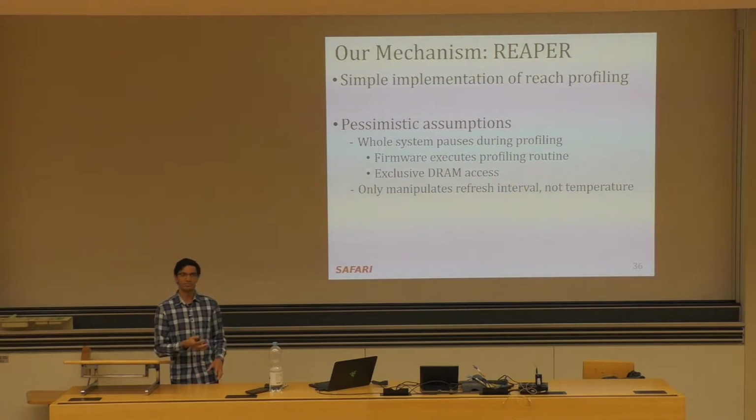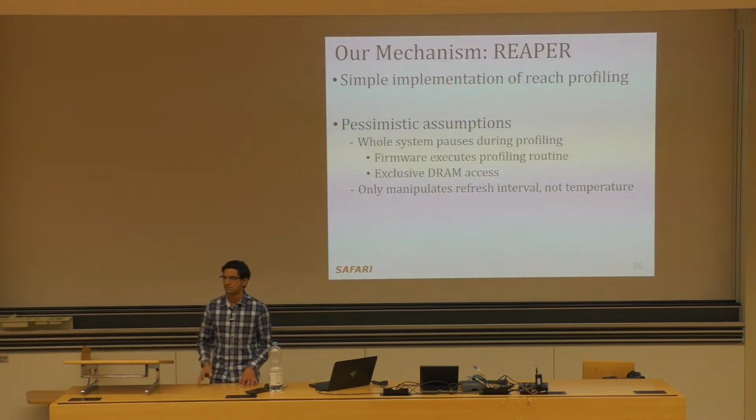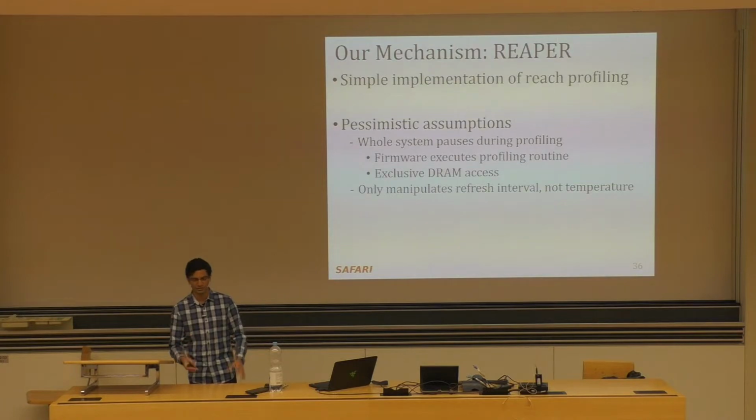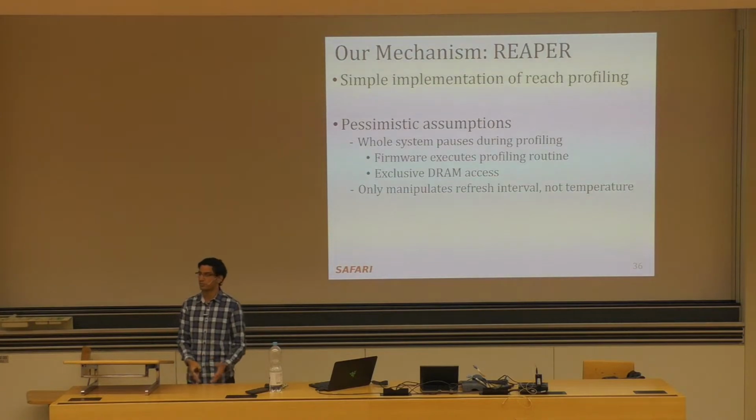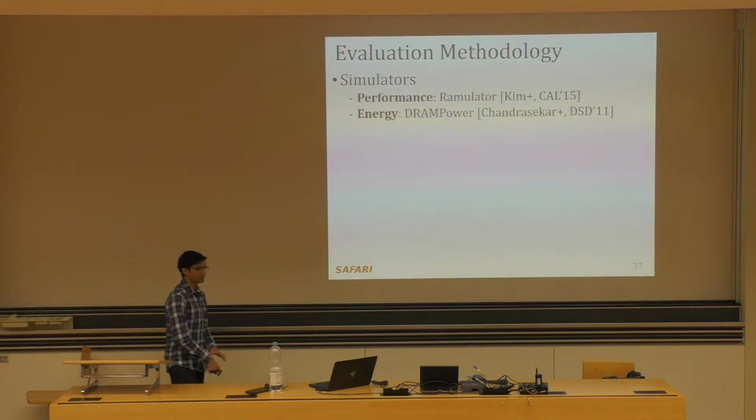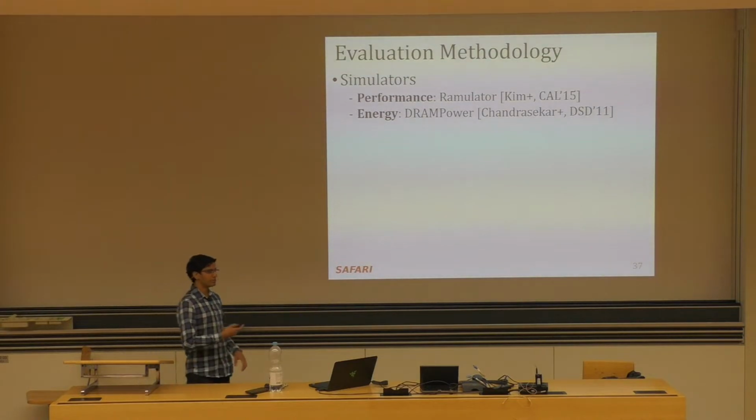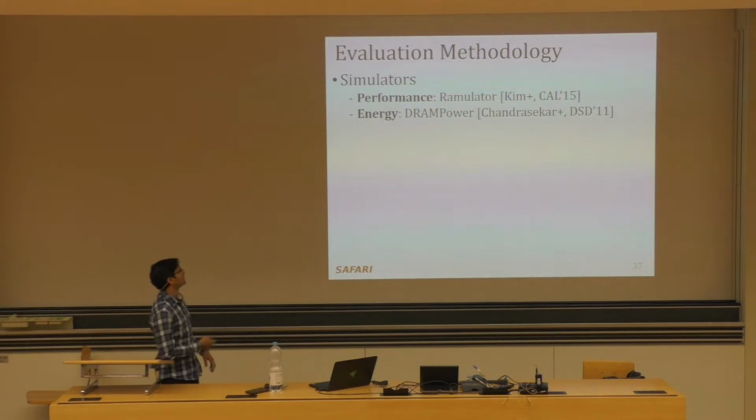And we believe this is a reasonable assumption for devices in the field, because controlling temperature, unless you have some lab setup and apparatus, might be a difficult thing to do. Whereas the refresh interval can be controlled potentially just by programming things in the memory controller. So our evaluation methodology is through simulation. We simulate performance using a simulator called Ramulator, and we evaluate energy using a tool called DRAMPower.